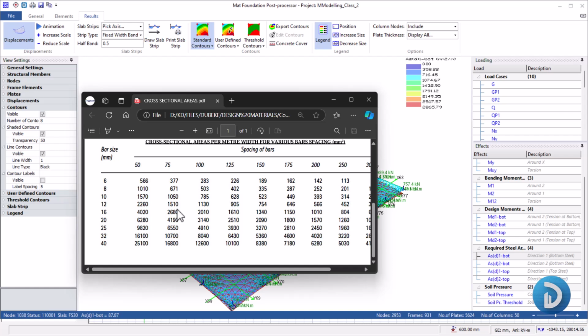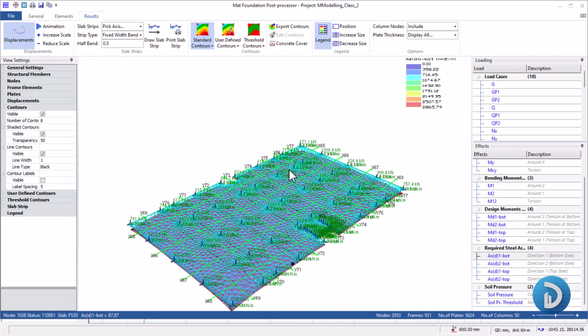There are ways you can remedy this even on Prota-Structure. So we also get to look at how you can remedy situations like this. Okay, so you don't necessarily need to construct with Y16 at 75 mm spacing. All right, so our slab did not fail. Then we also have to check the area of steel required on direction 2 at the bottom. So we'll click here. All right, and the maximum area of steel required at the bottom is 2017.